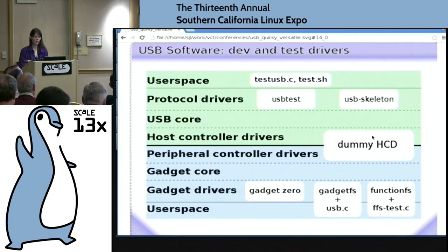So this can be a really great thing for testing your higher level drivers. Say you're writing something that has libUSB and a custom protocol on the one side, and FunctionFS and your custom user space code on the other side. You can actually work on this on your big beefy desktop Linux machine instead of having to do the initial driver development with your target hooked up. I think that could come in handy. Also, if you're debugging one of the class drivers for some reason, dummy HCD could be your friend.